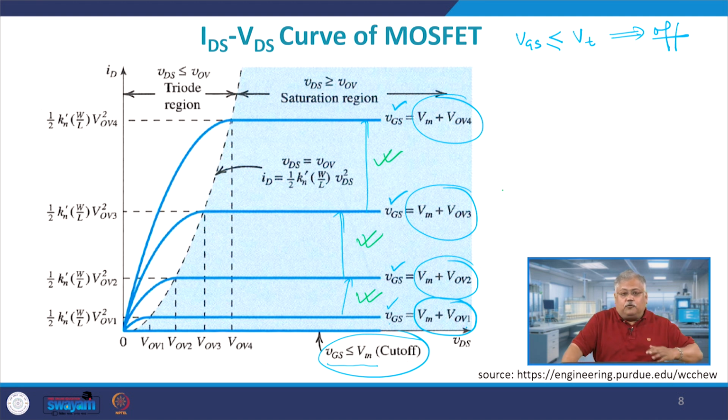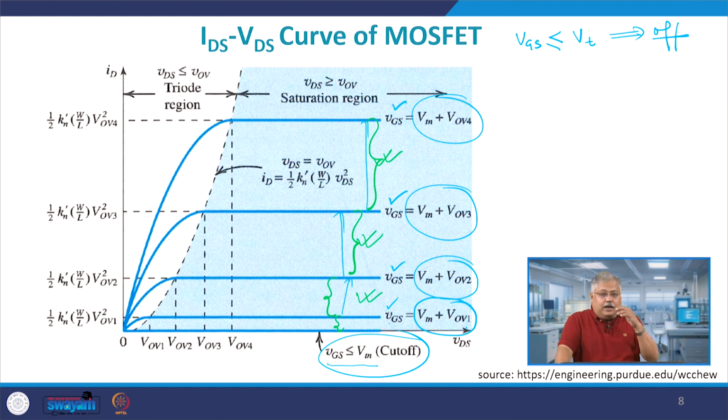So as the gate voltage increases, the differential current also starts to rise. You see, this difference is much larger compared to this distance, and compared to this distance. Correct? And the reason has to do with the number of charge carriers being attracted towards the interface.